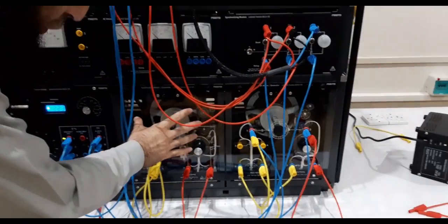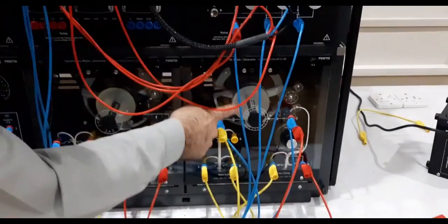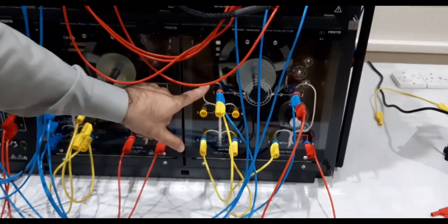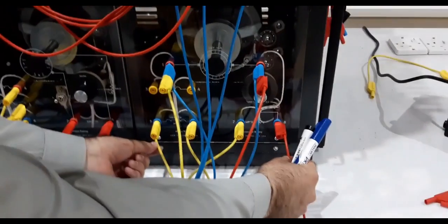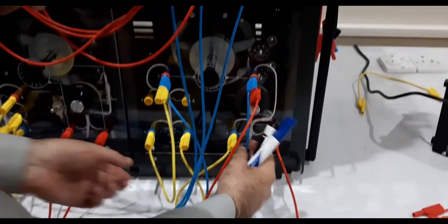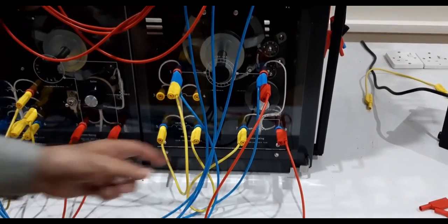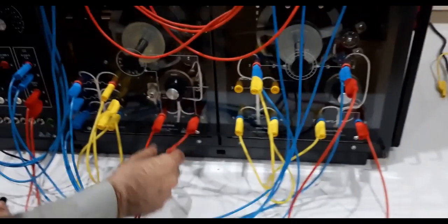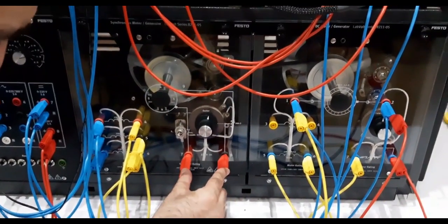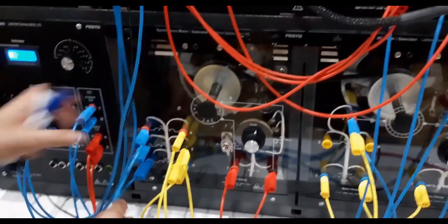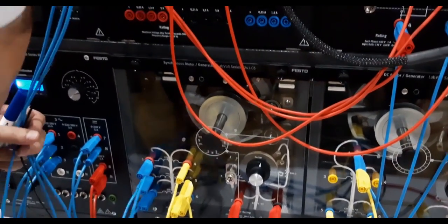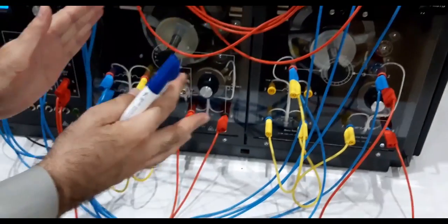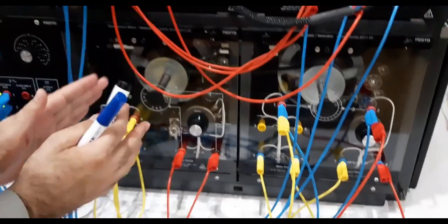So with the help of this demonstration, let me conclude or summarize it: we have a synchronous generator. We need to run this synchronous generator, so we run it by means of a prime mover, and the prime mover here is the shunt type DC motor, where we have an armature connection, also the field connection. The field is connected, there is a resistance in series with the field winding to vary the field current, and here we have a fixed DC supply that is connected to the main field winding. This is a DC, and this is the armature of the machine, which is 3-phase AC, and this is Y connected.